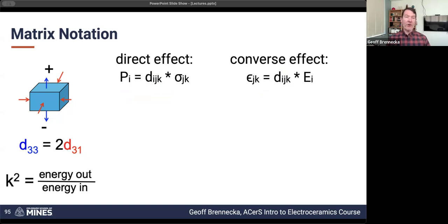And so I pointed out earlier the fact that Poisson's ratio means that when we have a solid, if we stretch it in one direction, so the example here in the blue arrows, it's going to shrink in the other two directions. You're used to seeing this with a rubber band, for example, or any sort of elastic behavior that is commonly found, you're going to see this kind of behavior.